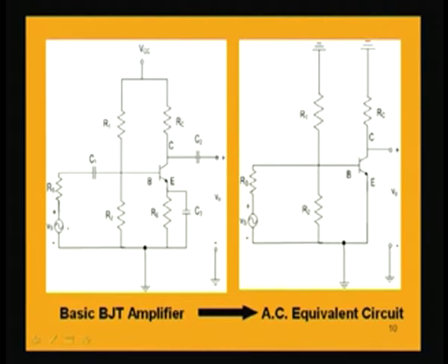So, for designing this amplifier, we must pick values of C1, C2 and C3 conveniently large enough, so that equivalently we can draw them like a short circuit. That is being done here. Instead of C1, C2, C3, we see short circuited paths. C1 is a short circuited path, C3 is short circuited, and the coupling capacitor also has a short circuited path.